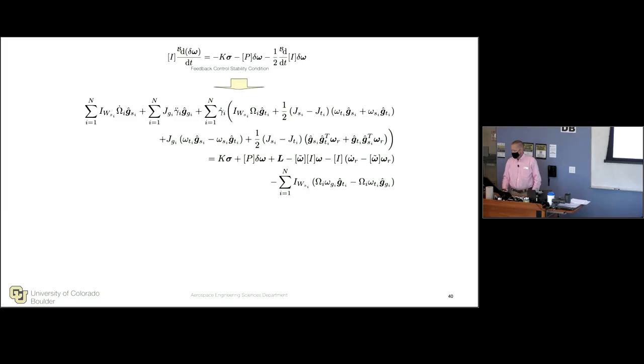And this is the new stability condition to achieve these closed loop dynamics, which will guarantee a negative semi-definite V dot. You could do Barbalat's lemma again, or LaSalle's invariance principle, and prove this like before. It's going to be asymptotically stabilizing if we can satisfy all these conditions. But before we had something a lot simpler. Don't you miss already the days of reaction wheels? That was the easy time where all of a sudden it's like, yeah, now instead of u, we have G_S times u and one extra term, and that was it. Now we get this stuff.